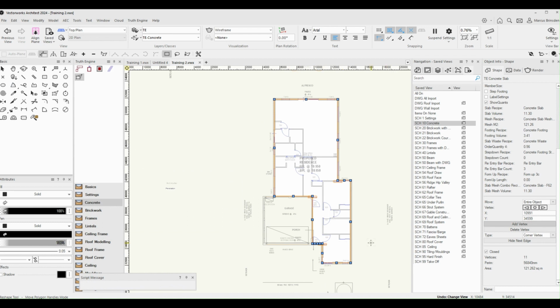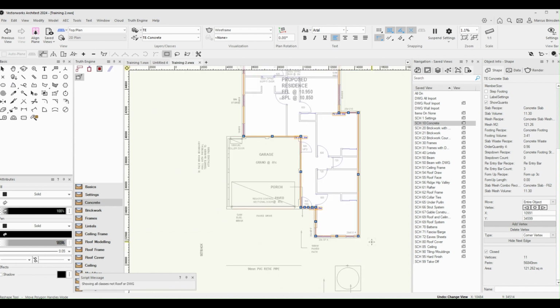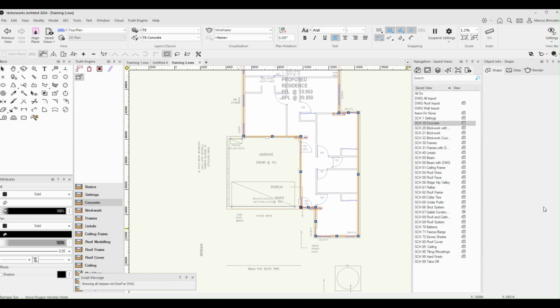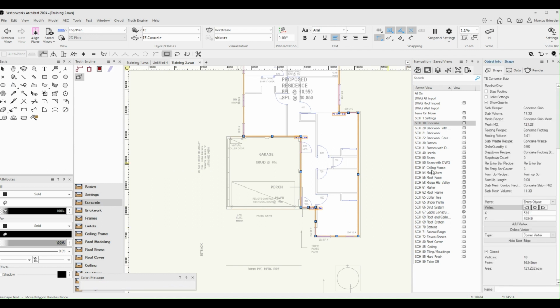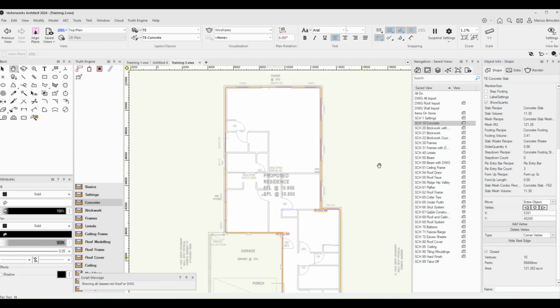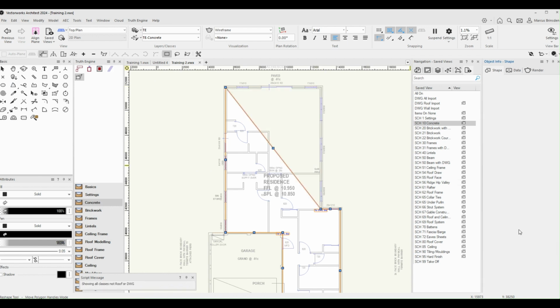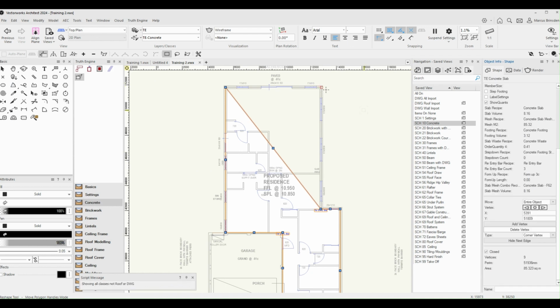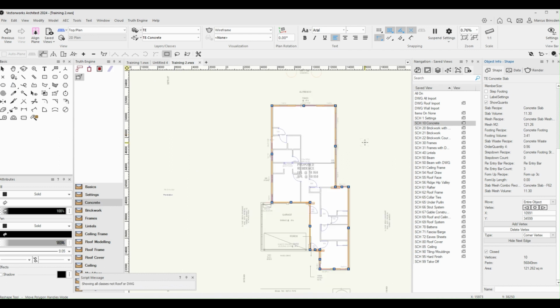And you can navigate around the polygon. If you see the nodes flash, so if you want to delete that vertex, when it flashes, that's the current vertex. So you can press delete. Let's take away that vertex. So with those tools and tricks that I've just shown you, you should be able to draw any polygon that you need to get the geometry right of your object.